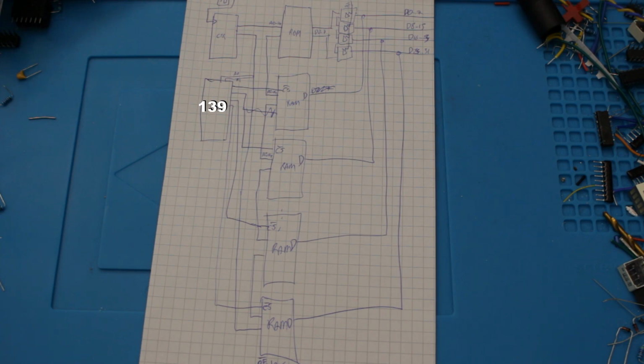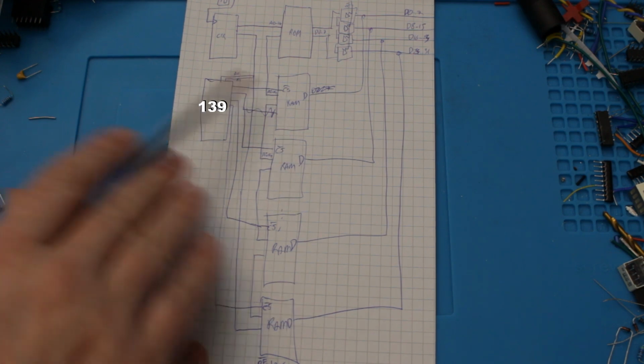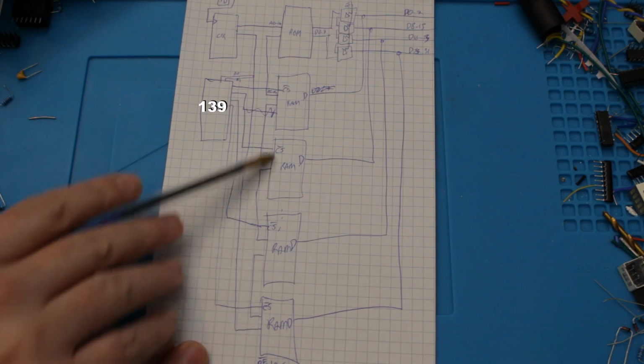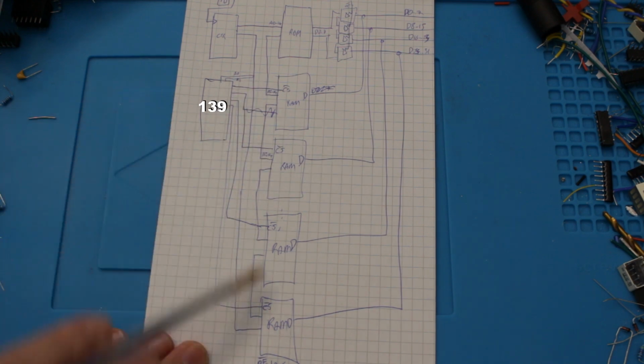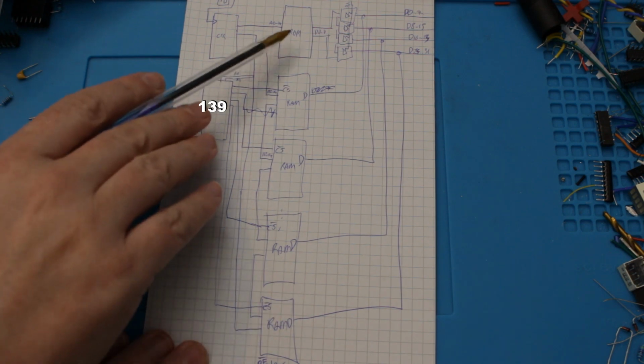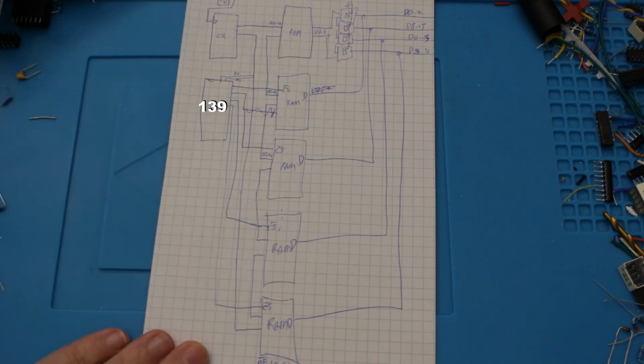And the idea is that we then just run it from RAM. And the RAM is going to have this kind of complex system. But the interleaving won't be a problem, because this circuit will essentially interleave the data for us while it's unpacking it from ROM to RAM. And again, the single ROM chip here will just contain a sort of regular byte stream of the instruction data. It doesn't need to be pre-processed in the same way that we will need to for the first diagram.